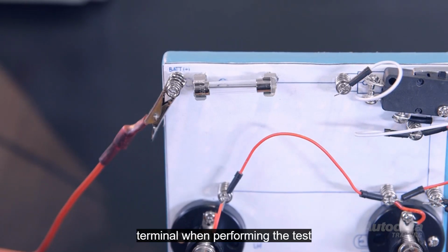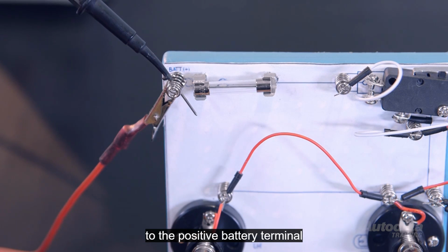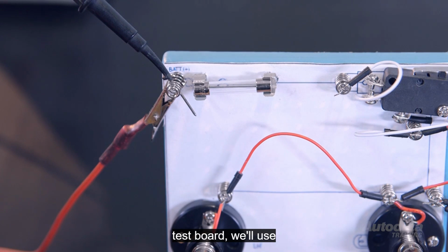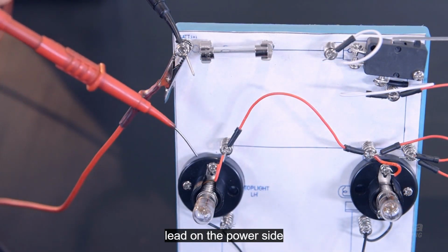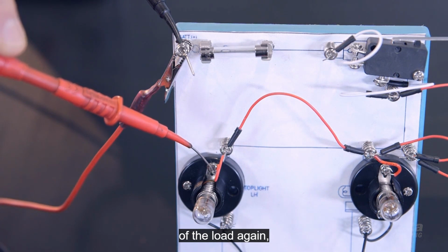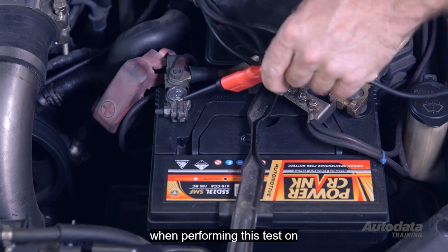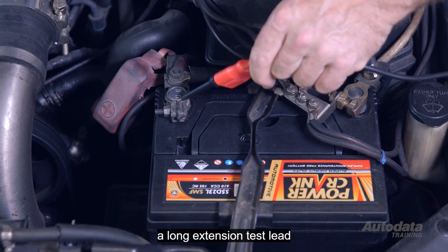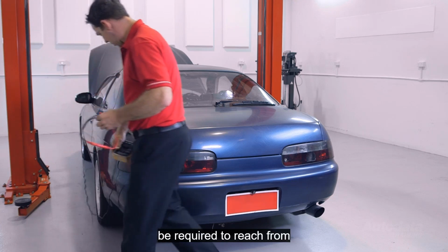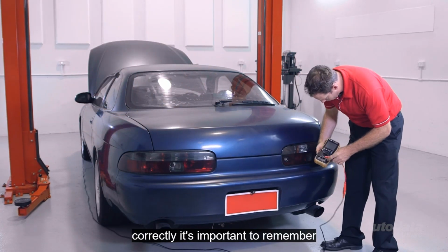When performing the test on a vehicle, attach the negative meter lead to the positive battery terminal as close to the post as we can. On our test board, we'll use the voltage source point. Next, we'll place the positive meter lead on the power side of the load. Again, attach this lead as close to the load as possible. When performing this test on a real brake circuit, a long extension test lead, like this one, may be required to reach from the front of the vehicle to the rear so each test can be performed correctly.